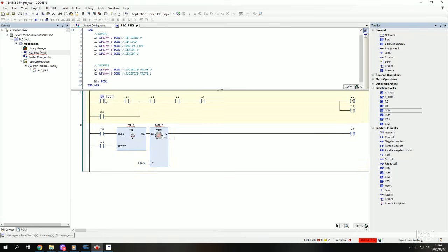When we click I0, before our piston rod advances, it should count 5 seconds. So this memory, we need to insert it here. So our I0 becomes M0. We are saying this I0 needs to memorize the 5 seconds delay before the piston rod advances.